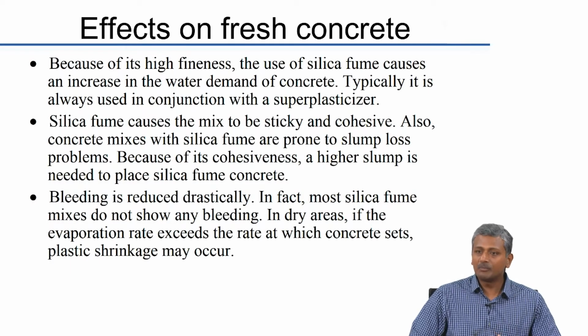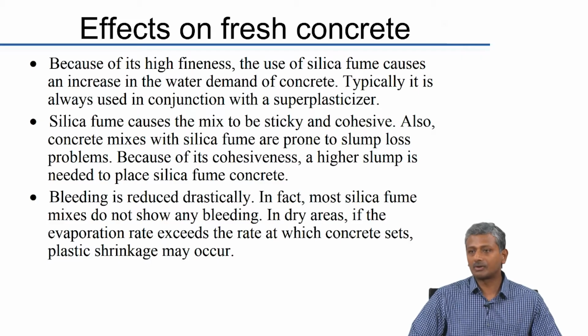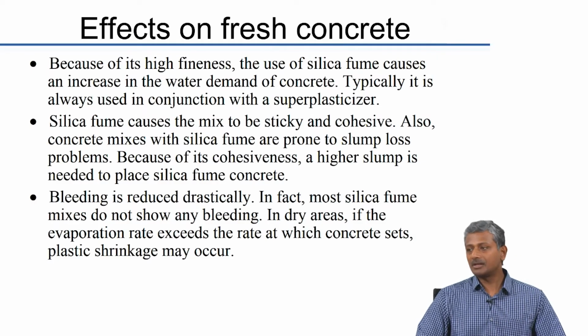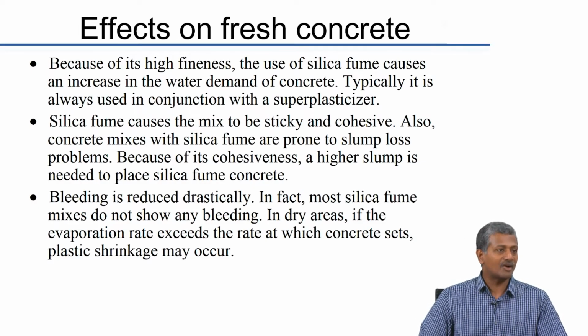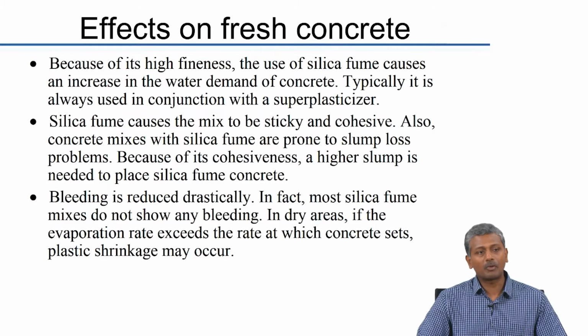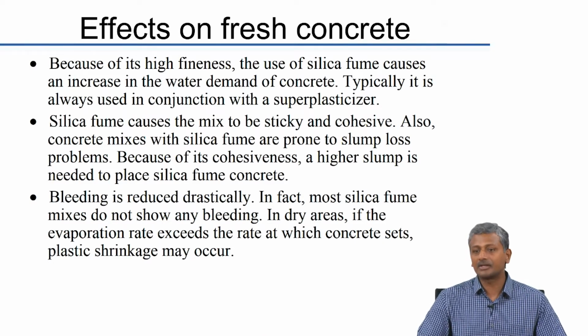Now, the main problem when silica fume is used is its effects on the fresh properties of the concrete. Now, hardened properties generally with silica fume, most of the properties are positive. I will talk about that in just a minute. But in terms of fresh concrete, because of this extreme fine nature of the particles, there is an additional degree of cohesion in the concrete. Okay, while that may be a positive attribute in certain cases, for example, when you are doing flowing concrete, in that case your self-compacting concrete is able to maintain the cohesion and prevent segregation, right.